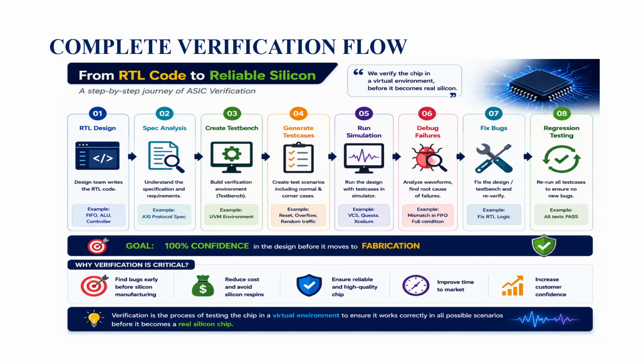We have to debug with the help of a single approach, and then we have to analyze the waveform, and then we have to check the driver logic, whether it is driving properly. After that we have to go to the monitor, to check whether it is sampling properly from the DUT. All these steps have been taken properly in the regression debugging.